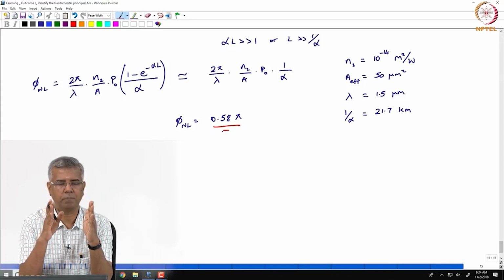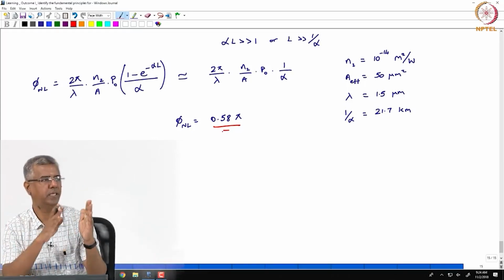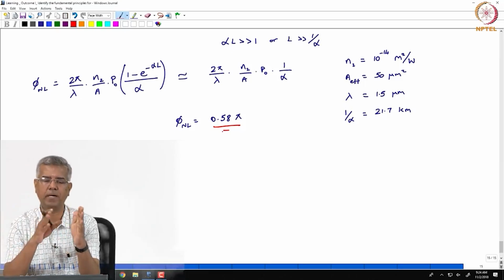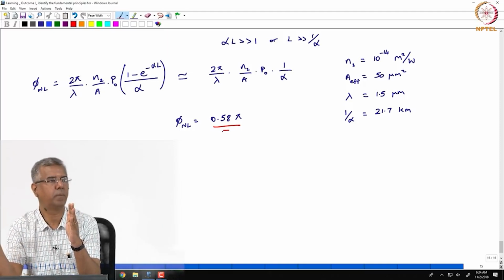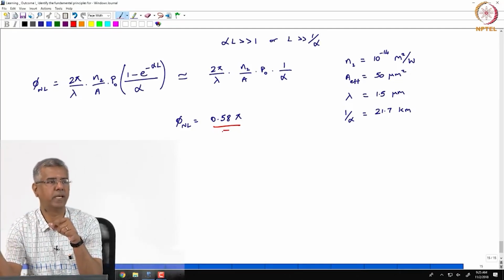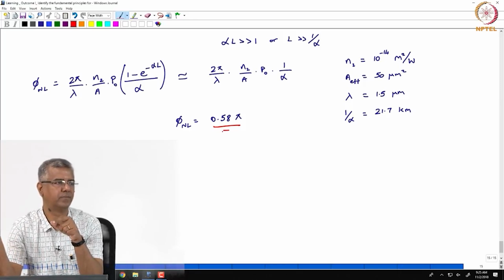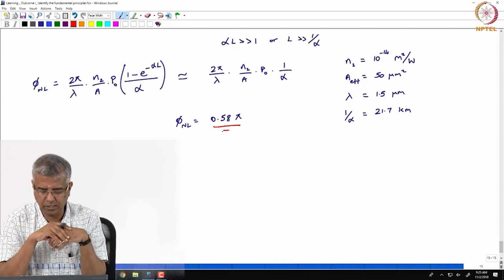Because of this phase, the pulse is actually moved over here, so part of the energy that's in this slot is actually showing up in the next slot. So if you are trying to make a decision whether this is a 0 or a 1, you will end up actually making an error, right? So there is only so much phase that you can tolerate.